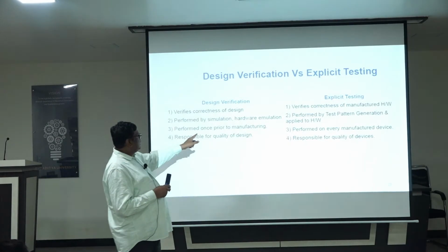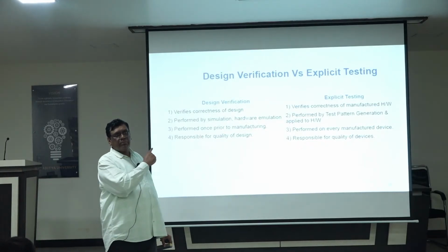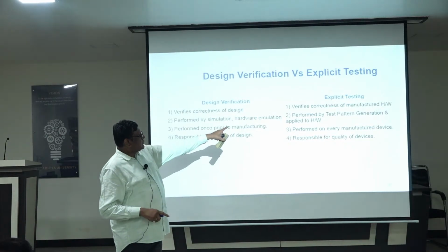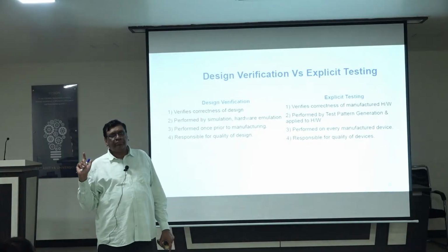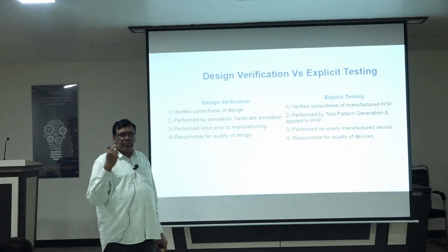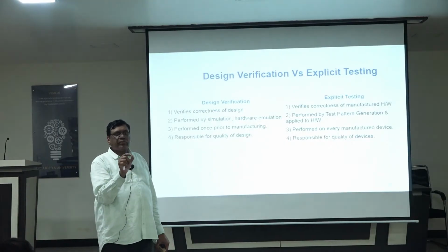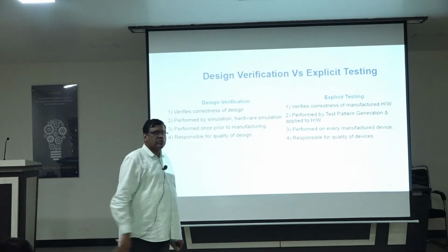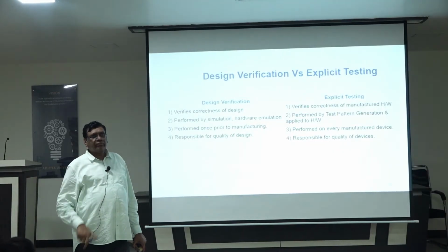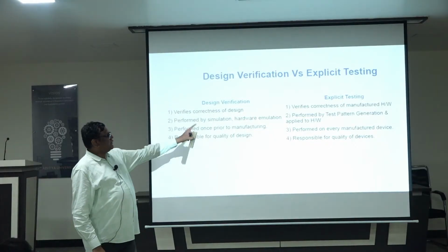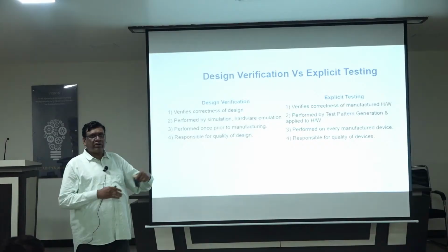Verification is performed once, prior to manufacturing. But testing has to be done on each and every chip you make. If 1 crore chips come out of the factory, each and every chip has to go through testing. With verification, only the first chip is verified, but all the chips have to go through testing. So testing is very important when the products are many.